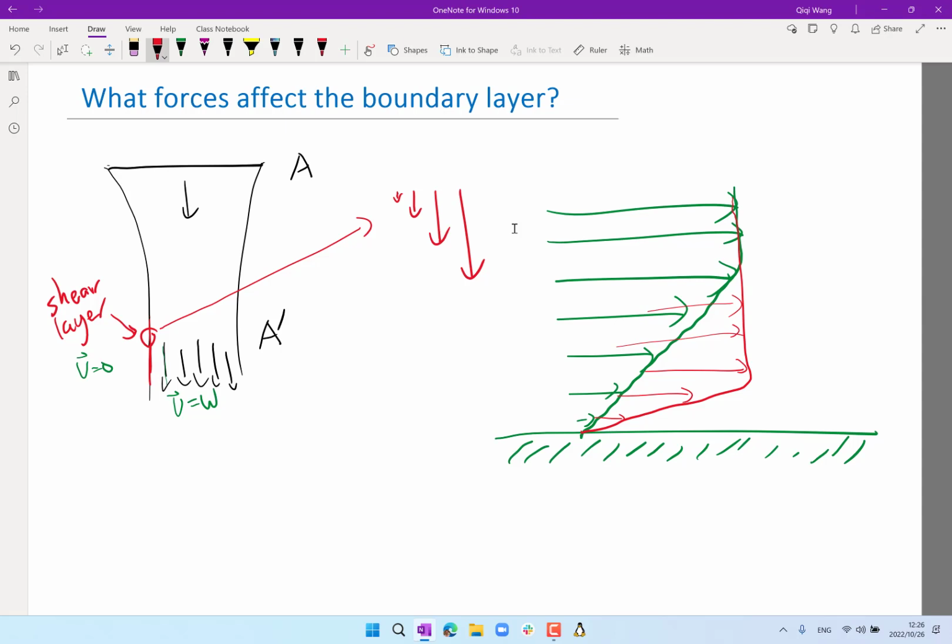And as we're going to analyze in the next lecture, there is a singularity point at which, if the pressure force is high enough on the already thick boundary layer, the boundary layer is going to separate. We are going to see exactly how that works in the next lecture. That happens only when the pressure force works with the viscous force, basically the pressure increasing as you go further and further downstream.